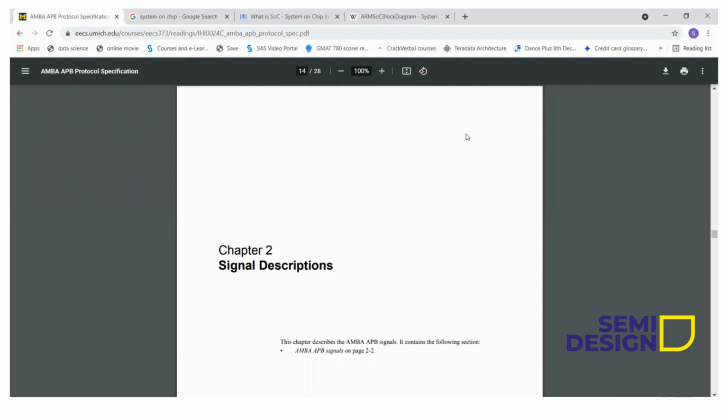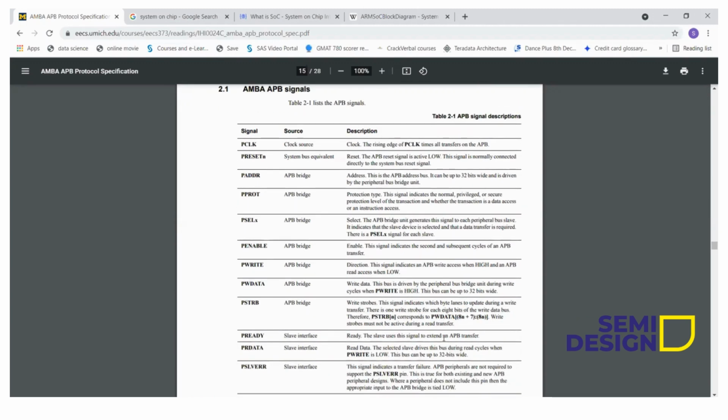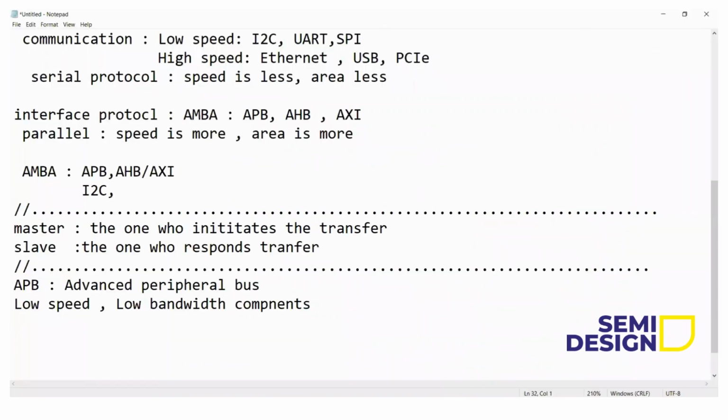If it is disconnected, then please connect again. So these are the pins here, and I'll be explaining them one by one. Two signals will be constant in all protocols. One is clock and another is reset n. Why is this small n used? In whatever signals, if they use a small n, it stands for negate, meaning this reset works as active low.